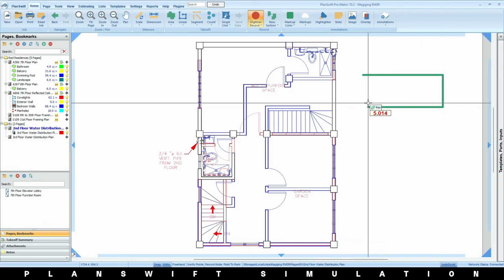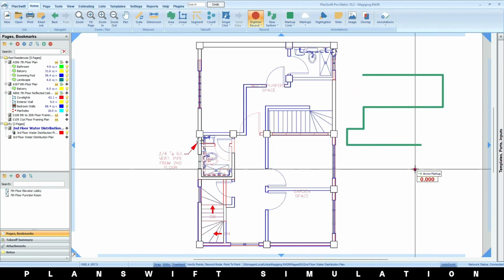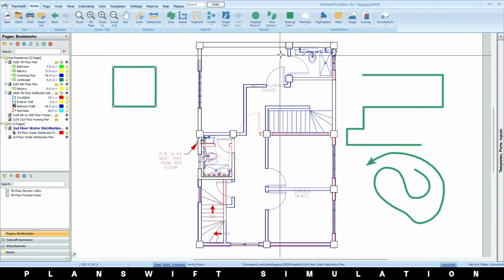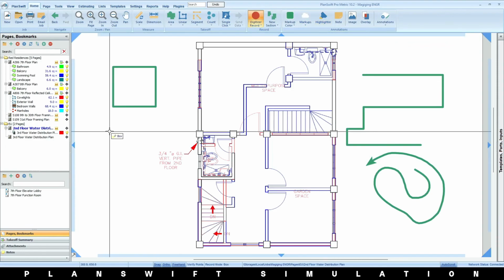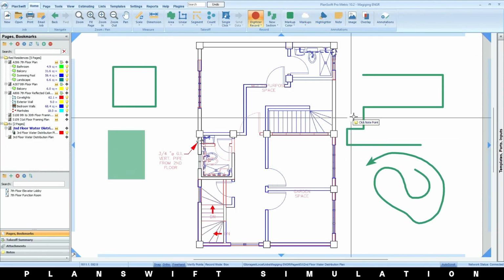The arrow and line markups are similar to the linear takeoff tool, plus the freehand tool works on them as well. The box and highlighter is similar to the box mode when using an area or linear takeoff. You can change the color of the markup by clicking the markup color.